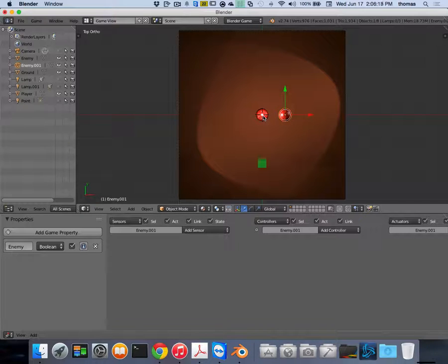So if you do a model or you import a model like a spaceship and you want your player to collide with it, right? Then you want to be able to set it up on one model and then duplicate it over and over again. Any changes I make to one model, when I do Alt D instead of Shift D, it duplicates it linked. So I make a change to one, it changes the other. That's an advantage. It's also a disadvantage. So be careful there. And you can unlink the models as well.